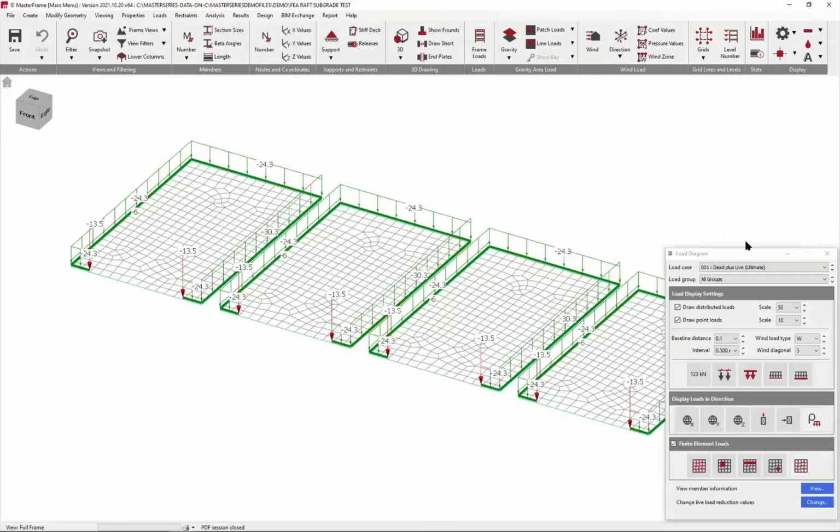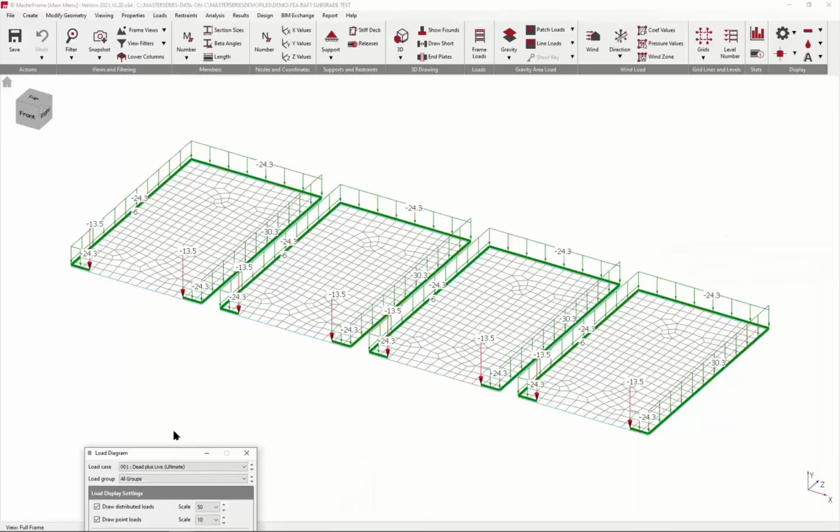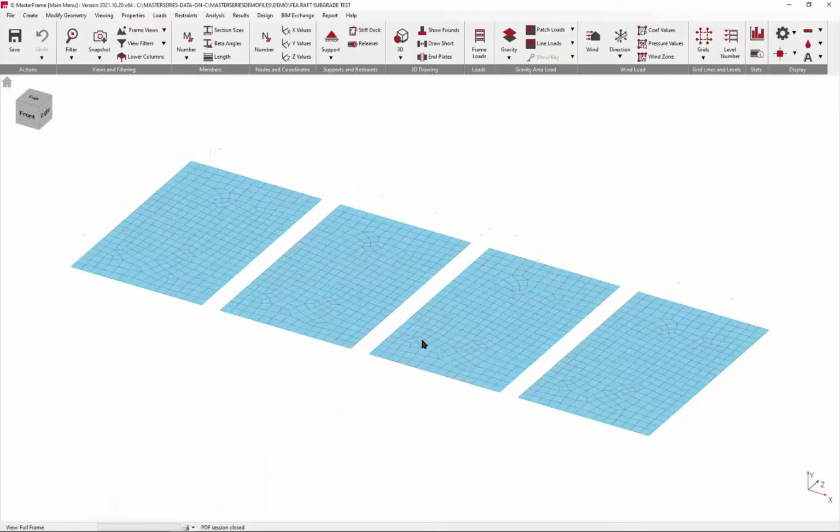For rafts, there are like little garages, something like that. Wall loads around the edges, a couple of point loads from a lintel. All identical, nothing too scary. Even if one side is slightly different from the other side, but that doesn't matter. Each one is identical. Same density of mesh, and reassuring that it creates the same adaptive mesh.